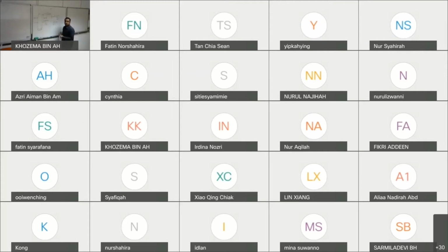It's better if you change everything into SI units. It will make your life easier. So 300 mm is 0.3 meter, 200 mm is 0.2 meter, and 25 mm is 0.025 meter. Now everything is in SI units: meter, watt per meter degree Celsius. Then 0.3 times 0.2 is going to be 0.06 meters squared.